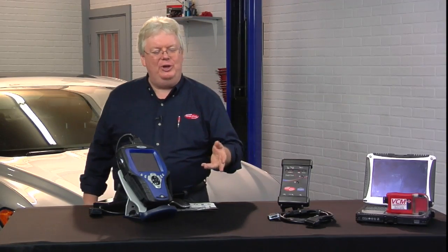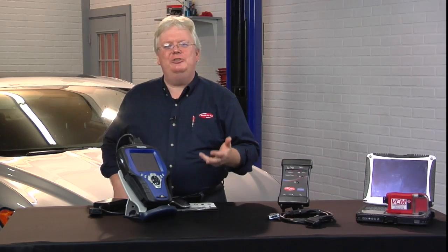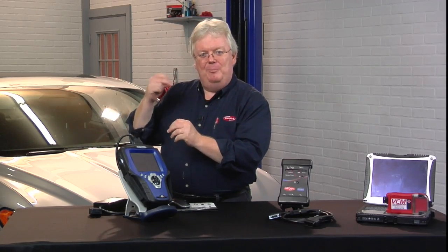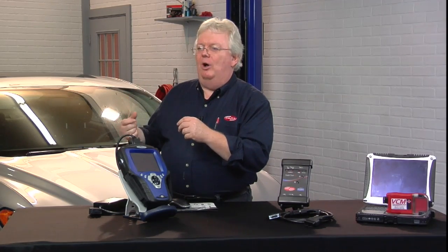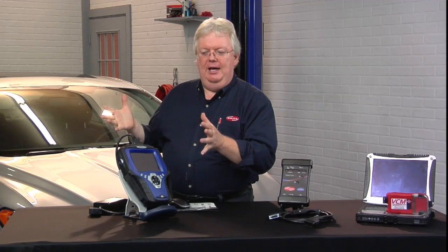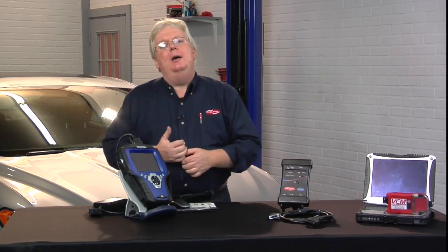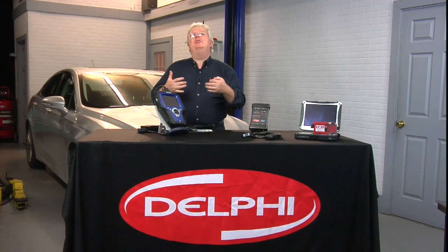And I ran through several tanks of gas, stopped for several nights and so forth in my training tours. So it can be frustrating getting monitors to run, and others will just, man, I'm just trying to clear this code and do some work and the monitor pops right away. So it's all over the place, truthfully. What you want to do is look to see what the monitor requirements are. So the enabling criteria for codes, for example, well, there's an enabling criteria for monitors.